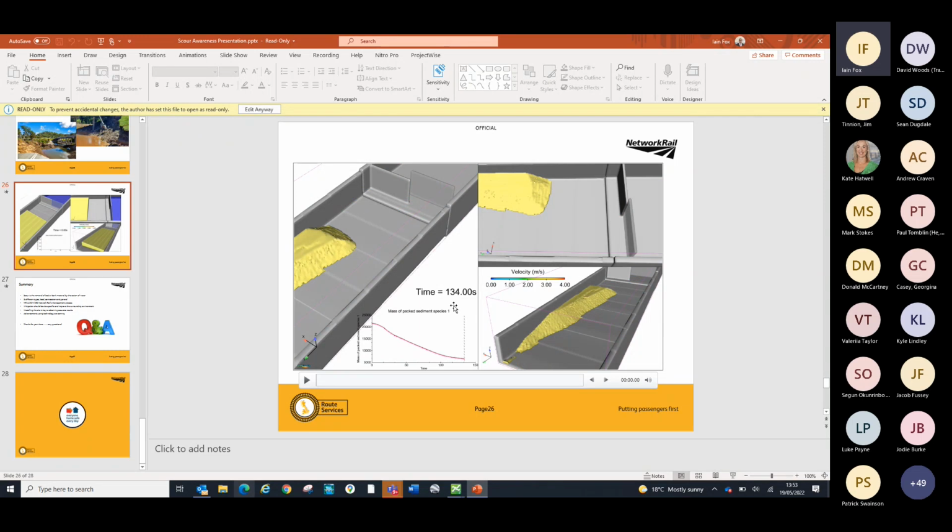One of the things that always astonishes people when I tell them is that when we do have a flood going down a river, the scour hole opens up and is its deepest within 10 or 15 minutes of that flood happening. After that, it's filling itself slowly back in, because you know the flood can move an amount of material, but when it's at that velocity and that energy, it moves it very quickly. So there you go. Thank you for your time.